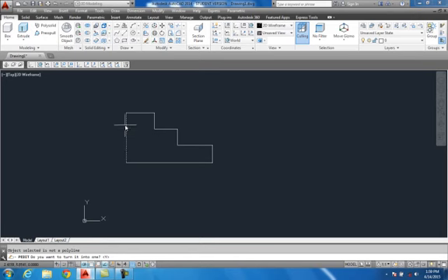Well, when I click on this, this is a line. This is not a polyline, but it asks me, do you want to turn it into one? And Y is for yes. So hit enter, and click your join button, and then you go here and join all of it up. After you join it, right click to enter, and now you can go in there and click on it and see how it's all one piece.